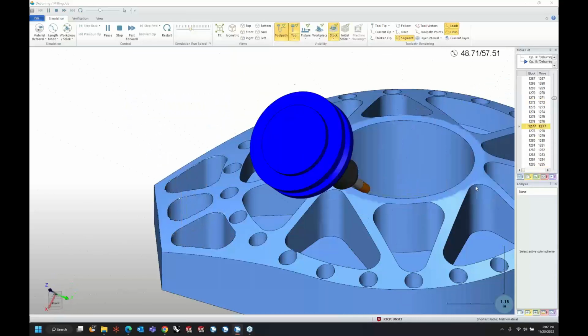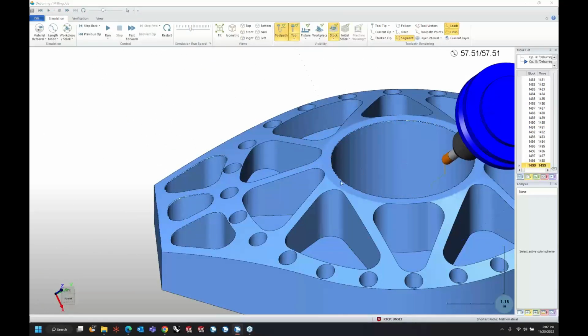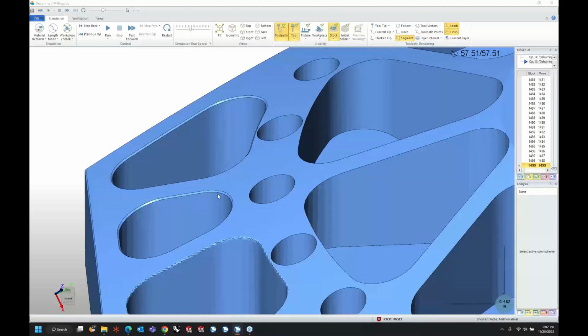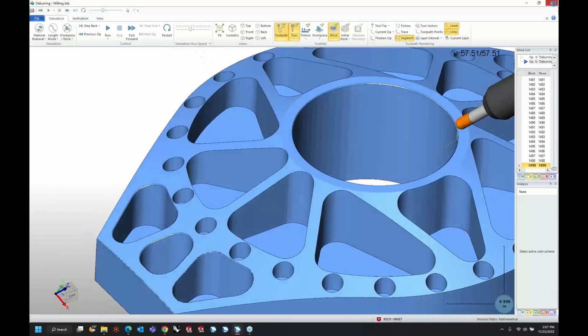Yet unfortunately, the simulation runs kind of at a low resolution. And then lastly, you have your contact point. So you can actually set a contact point for going around a part. Once this automatically refines there, we should see a little better edge. Now, deburr is actually a really simple toolpath to use. Not a lot of selection, not a lot of things to know about it. So you can see kind of the differences there, all pretty much doing the same thing.